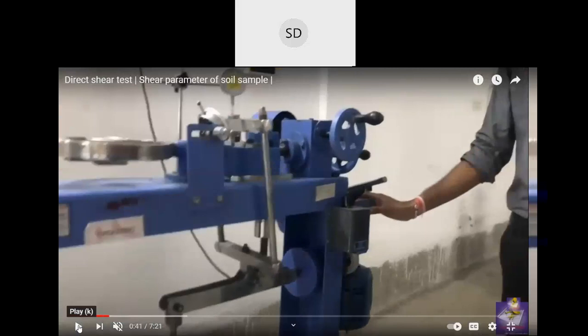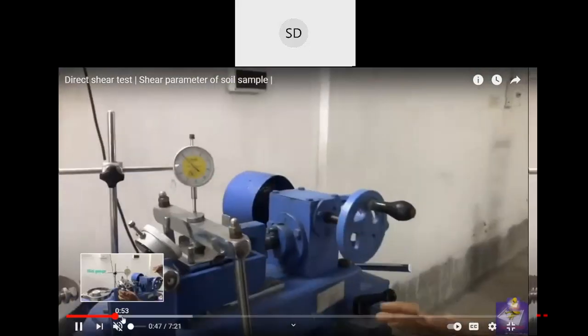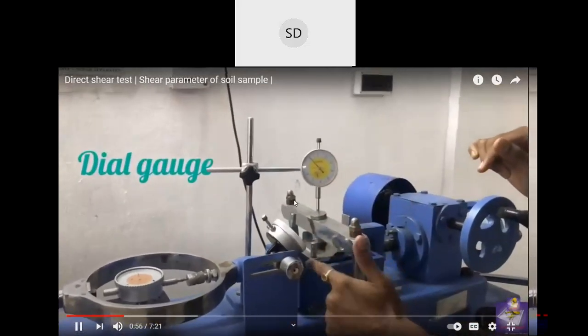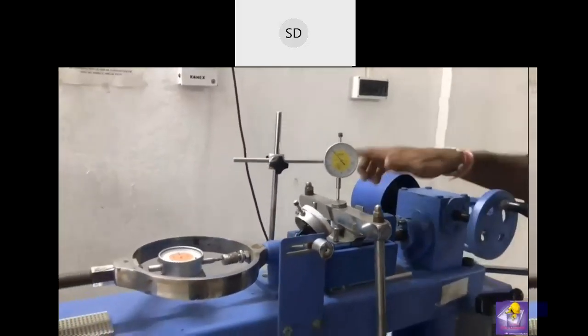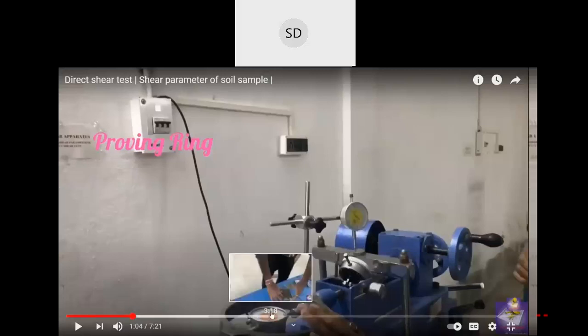This is also available in our lab classes. I don't know whether you have performed this test or not. See here, three dial gauges are attached. This dial gauge takes note of the vertical displacement, this dial gauge takes into consideration the displacement caused by the shear stress, and this dial gauge is for the loading condition, to check how much load is applied through that plate.